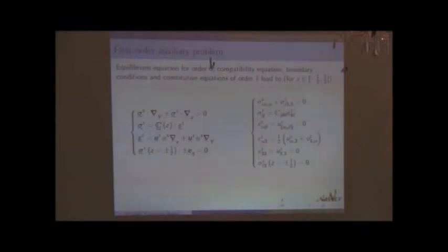What is new here is that in the previous auxiliary problem there was only one contribution, which was the divergence of sigma 0 with respect to the z coordinate. Now the unknown is sigma 1, and you take its divergence with respect to the normal coordinate, but you have a loading which is related to the variation of the previous stress field we just determined. So this is a very new feature of this auxiliary problem.